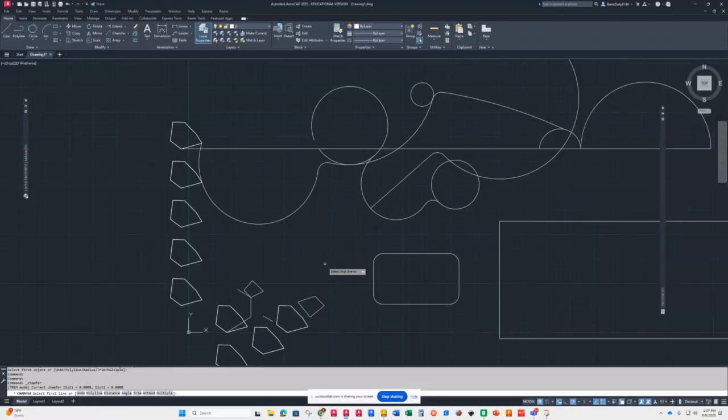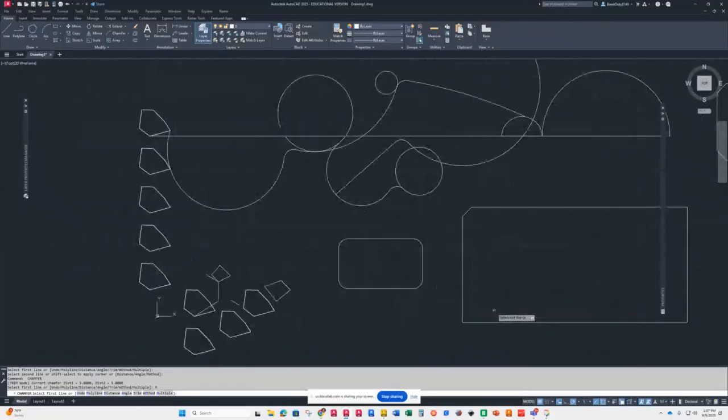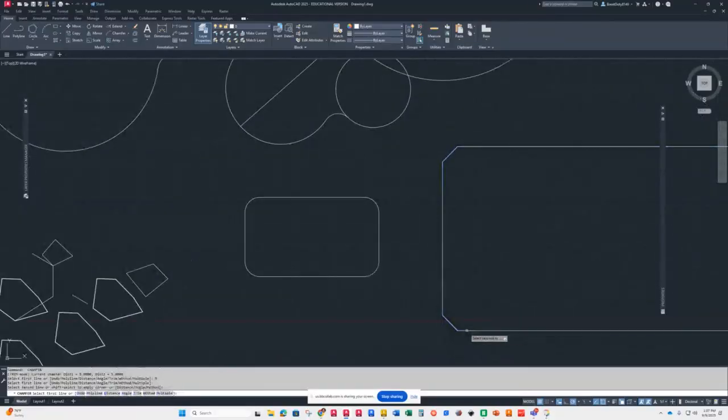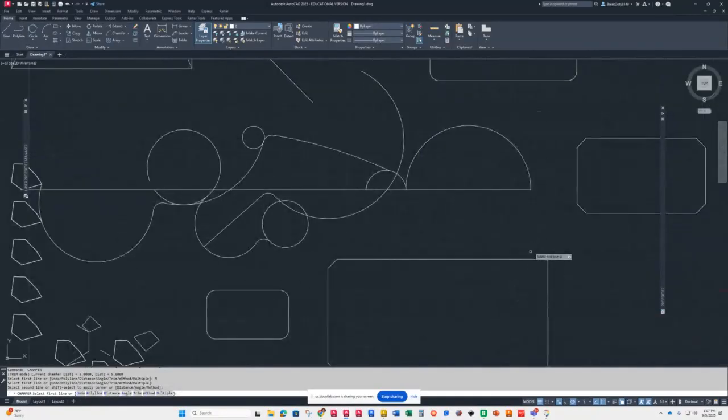You either need to know the location of both ends, or you have to know the location of one end and an angle. Well, you have that option in here. You can either go with distance or angle. And I usually just show the distance one because that's the typical one we use. So if it's 5 and then 5, then you would just pick the thing that you want to chamfer. And just like on the other one, if you go into multiple, you can do multiple chamfers. Just like in fillet.